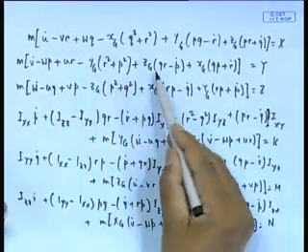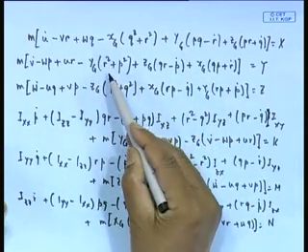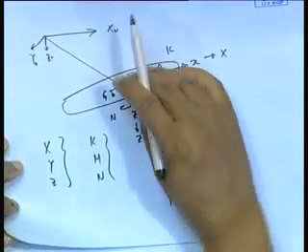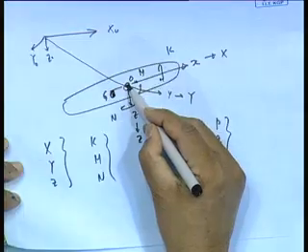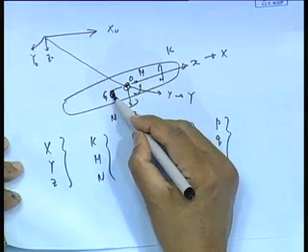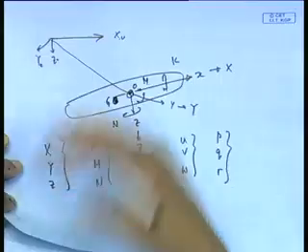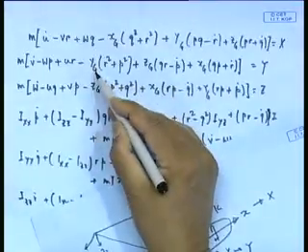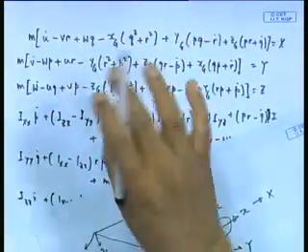Then because y_G, z_G and x_G are not necessarily 0, there are additional forces coming for rotation. Remember, the body is something like here, but rotating about this point, because I am defining the forces about this axis, but the rotation is about this point. So as it does, there is an additional component that comes, p square plus q square into those distances, that is a kind of inertia force, the rotation square into the distance.